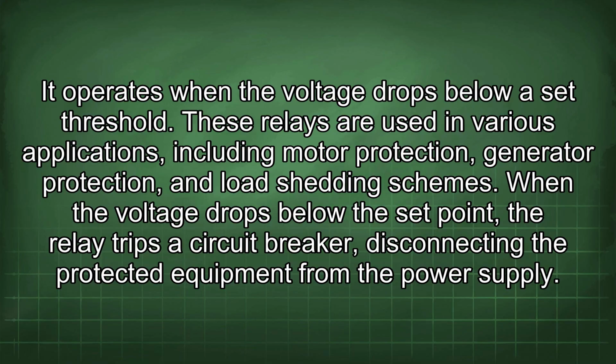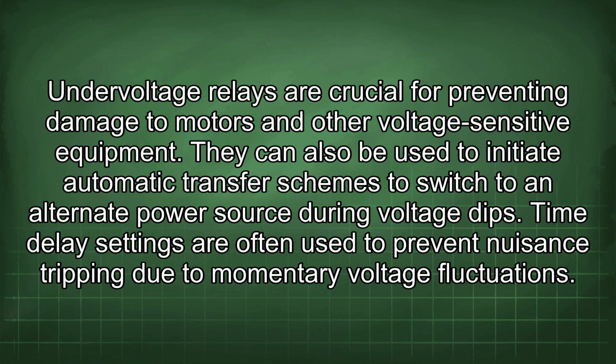power supply. Undervoltage relays are crucial for preventing damage to motors and other voltage-sensitive equipment. They can also be used to initiate automatic transfer schemes to switch to an alternate power source during voltage dips. Time delay settings are often used to prevent nuisance tripping due to momentary voltage fluctuations.